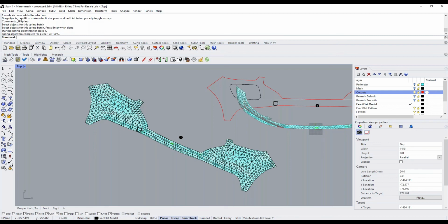Okay, next question. Is Exact Flat used in the metal forming industry? Are there material settings already available for this? So the answer to your question is yes. If you are making metal or thermoformed objects, you can use Exact Flat. There are a couple of other considerations. First of all, you need to get your material tested for the type of stretch. Metals are generally isotropic, so they will stretch the same in all directions, but they may have a thickness.